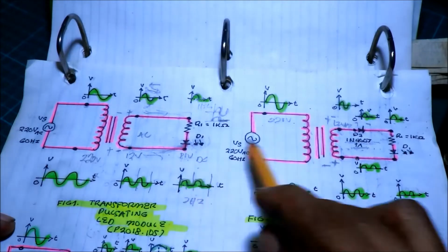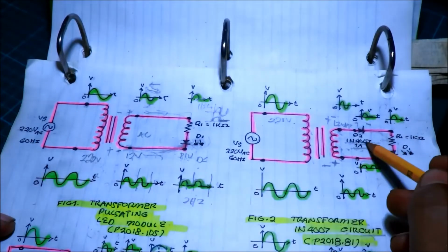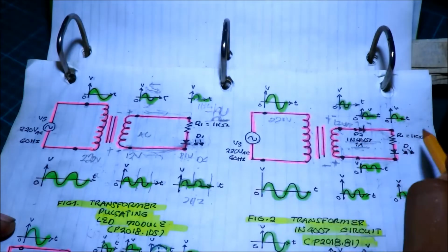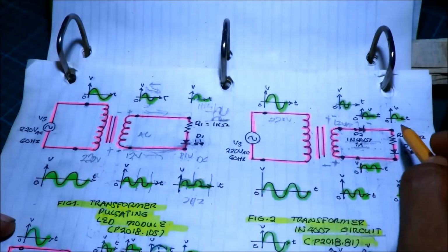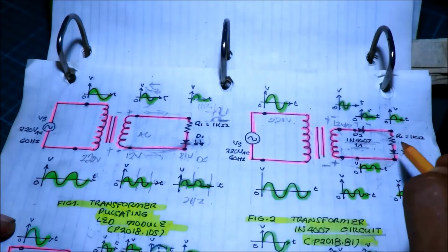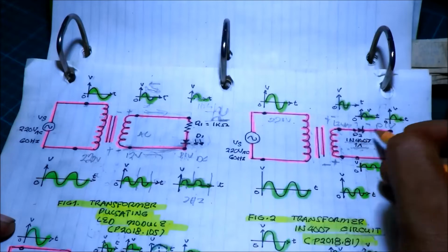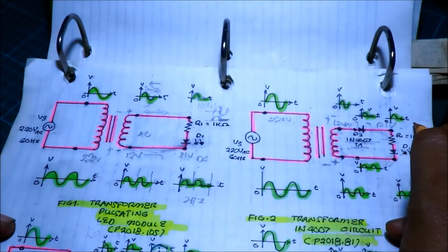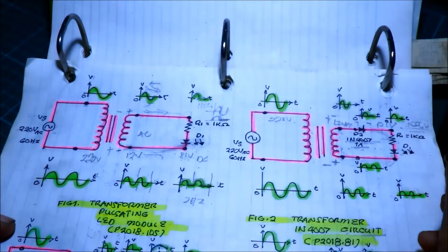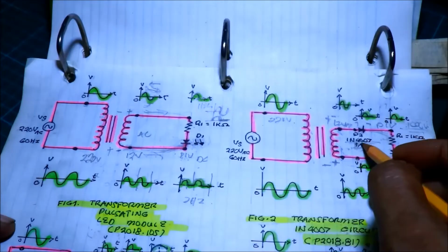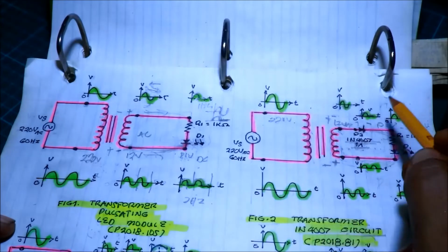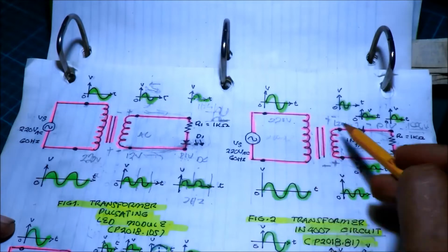What's the difference with the two? It is much more durable or efficient, because we have now a diode that can protect the LED from burning due to the reversal direction of the wave. The peak inverse voltage of this diode is a repetitive voltage according to the data sheet of almost 1000 volts, up to 1000 volts. It has a current rating of 1 ampere. That is the current it can handle, 1 ampere. And our transformer, I think we got only 200 milliampere, so it's safe.